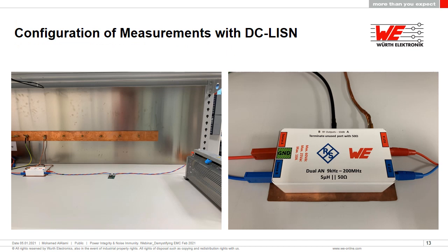Okay, so that was the time domain measurements. Let's look at the frequency domain measurements using that EMI receiver. We used actually the, what was it that we used at the time? Oh, the ESRP EMI test receiver, also from Rohde and Schwarz. Another fantastic piece of kit. So for that, the setup was using that dual LISN I mentioned to you before. So the dual LISN, you can see it has got two RF outputs, and with those Mini-Circuits power splitters and combiners that we mentioned before, we could look at common mode and differential mode also separately.